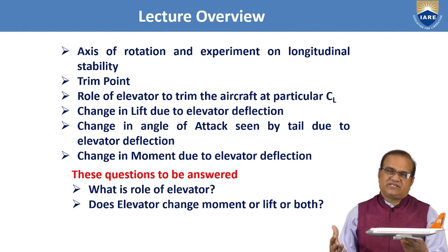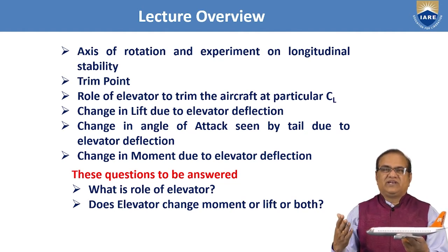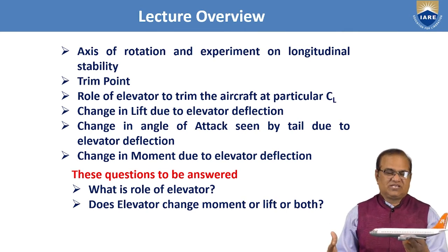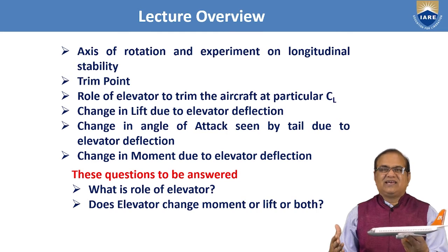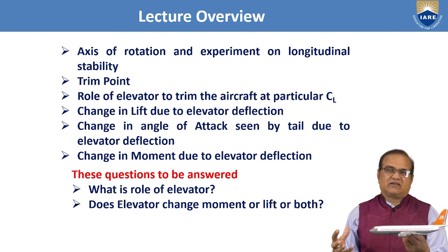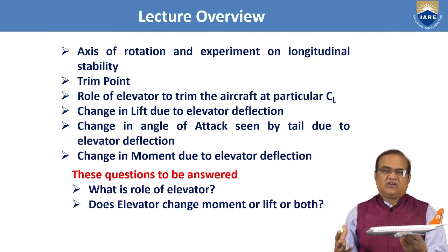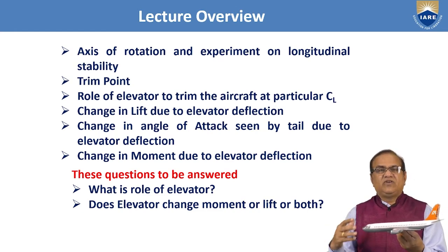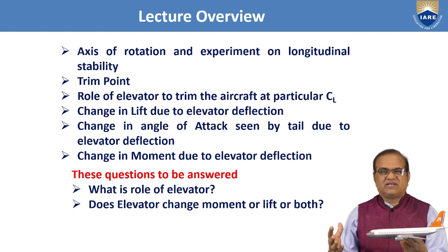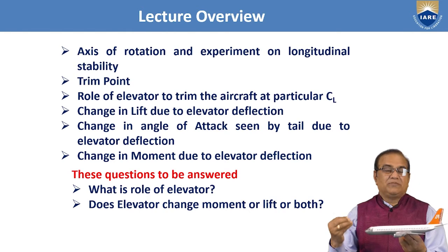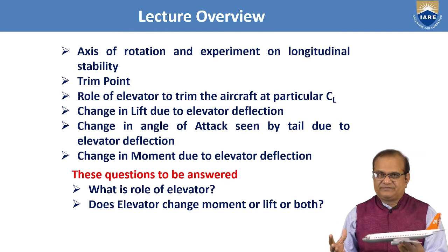Till now, I have discussed the basics of stability, types of stability, that is static stability and dynamic stability, and types of motions. I have described the 6 motions. Out of that, only 2 motions are dynamically stable, and 4 motions are statically stable. We all are working for dynamic stability, but the basic precondition to have dynamic stability is that any aircraft should be statically stable.